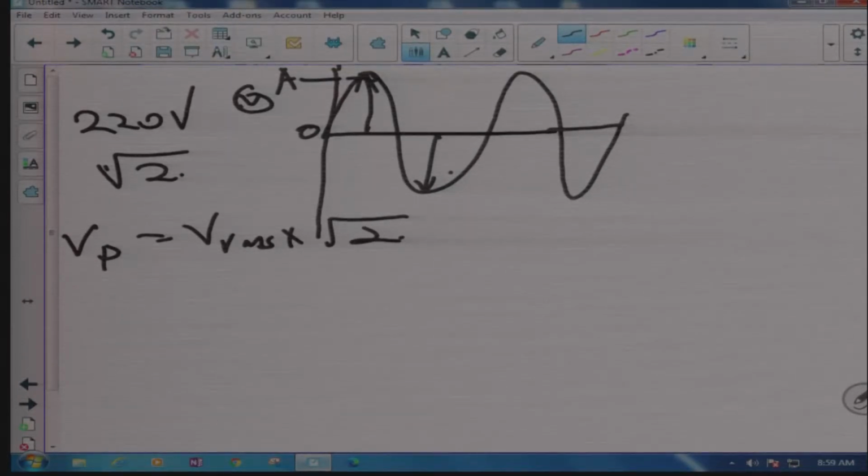Be careful about that. When you do measurements, any measurements, your voltmeter always measures an RMS value. If it's an AC and you want to draw it, we only draw the peak value. We never draw an RMS value. Always multiply whatever you get with the square root of 2. That on its own tells us more about this.